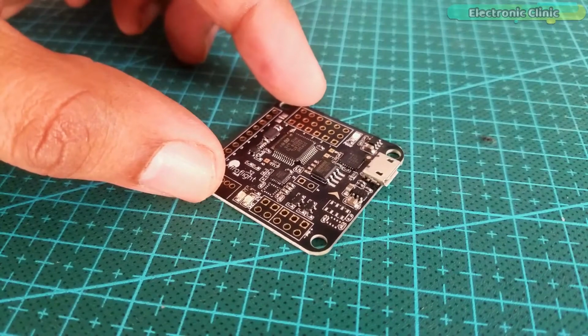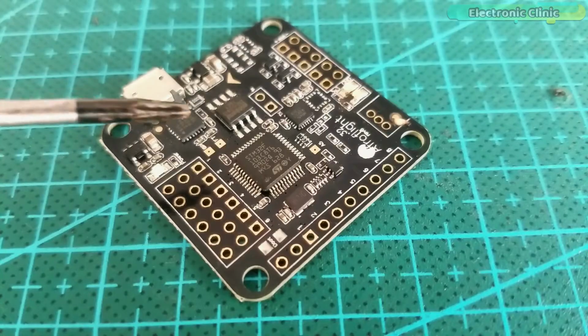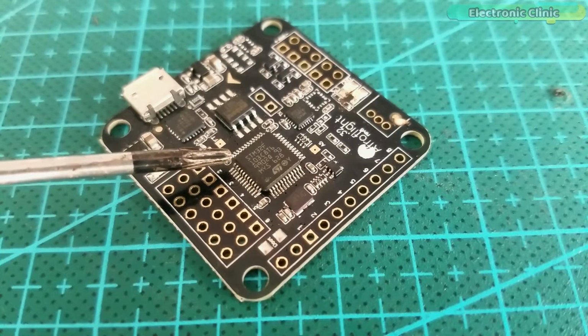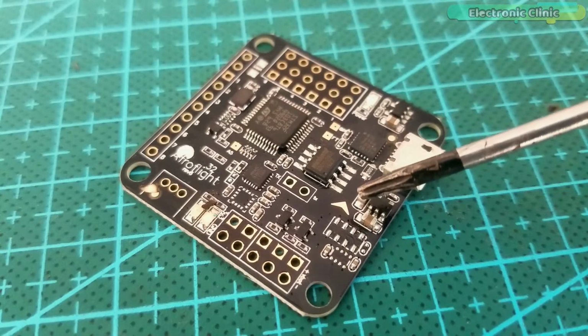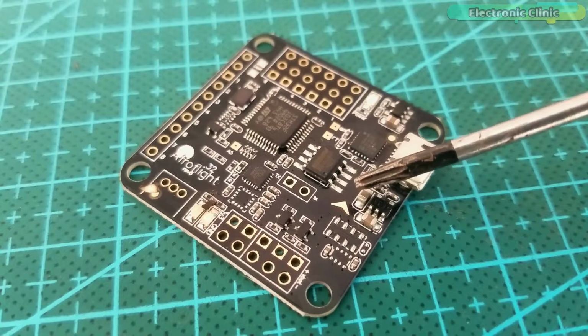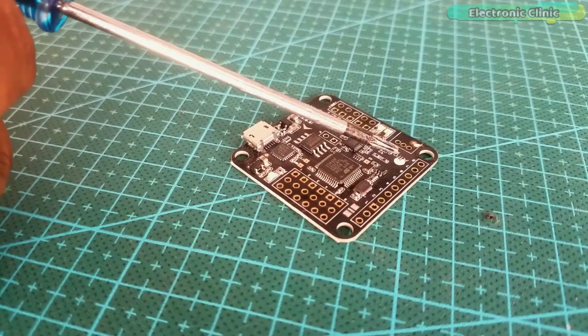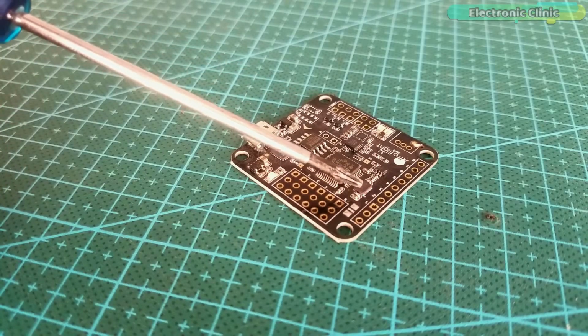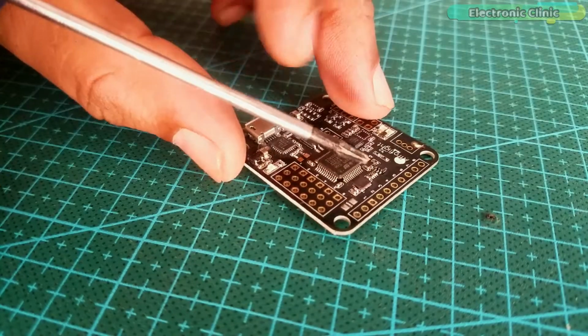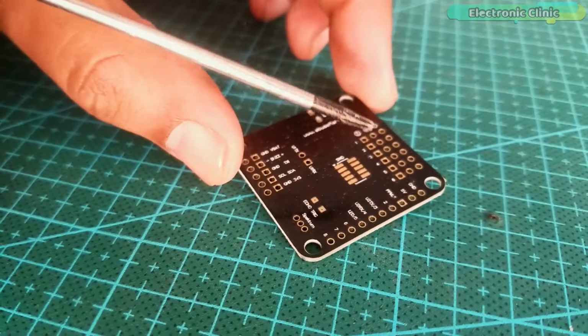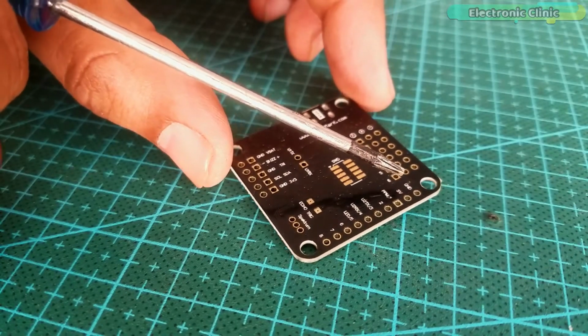This is the Naze32 Rev6 flight controller, which is based on the STM32 microcontroller. On the board you can see this arrow sign, which should be towards the front of the quadcopter drone. With these headers we connect our wireless receiver, which in my case is the FlySky FS-i6. On the back side you can clearly see all the headers are clearly labeled.